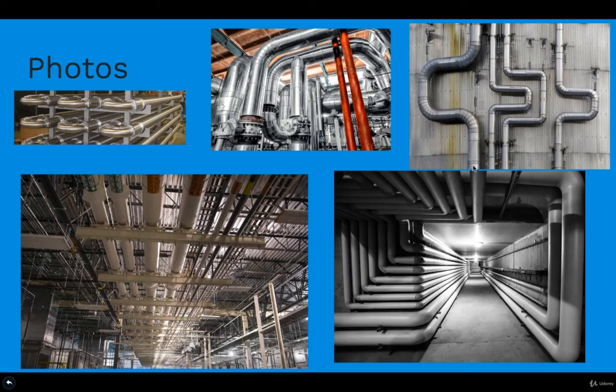Let's say we have 120 Celsius degrees right here. You don't want to lose it all to the atmosphere. If you let it alone, it will go maybe down to 30 Celsius. But if you have insulating material, maybe it goes from 120 to 110, and there is not that much loss. If you need the temperature for further operations, then you will not need a heat exchanger and so on. You have different sizes, of course, and also very important to consider that sometimes they are ducts. What are ducts? Essentially air flows through them.